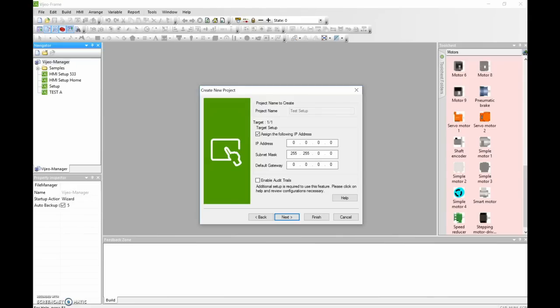And so it's essential that if you have different IPs for different HMIs and different PLCs, that you keep an Excel spreadsheet of everything in each IP in one place, so that you can reference those IPs, see which IPs are still available, and then you don't have conflicts arise with another PLC or another HMI or another drive.